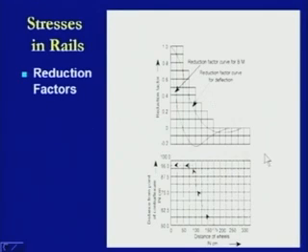Similarly, we have to look at the relief of the deflection. Now, if we take any rail section and some load is applied at this point, there is some stress induced at this point, and there is another wheel at this location, again inducing some load and a deflection at this point. As we have seen, because of the overlapping of the bending moment diagrams, or similarly the deflection diagrams, there will be a relief. So, we have to look at by what amount this relief can be there because of another load working in the adjacent condition.